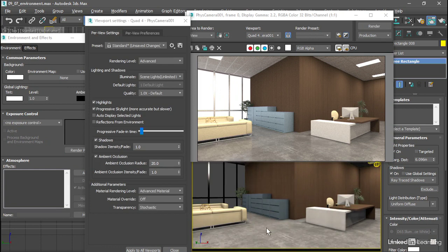Now the good news is that we can separate the rendered background from the rendered environment lighting and not sacrifice anything. And the solutions for that include creating a skylight or using a special map in the environment slot. The skylight method is renderer specific. You'll need to use a different type of light depending upon which renderer you're using. To be as renderer agnostic as possible, we'll use a shading node in this environment map. We'll take a look at that in the following movies.